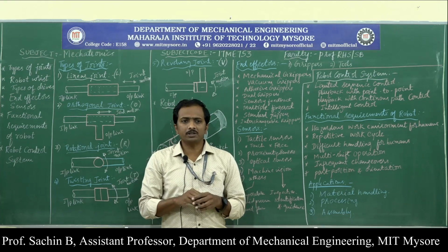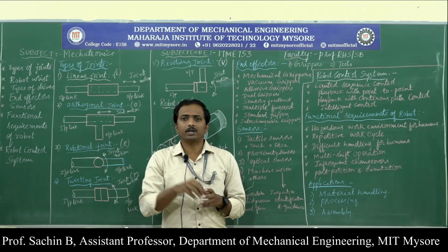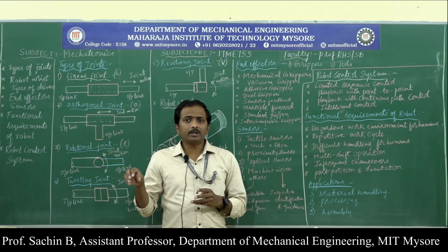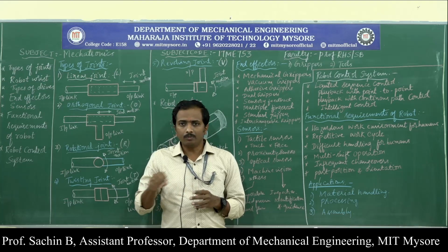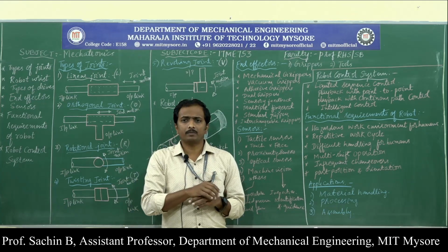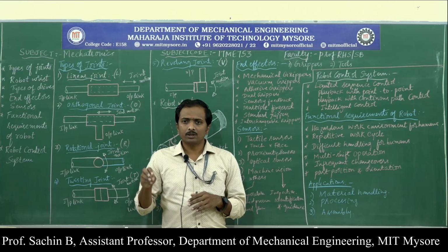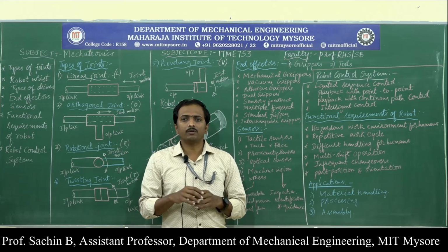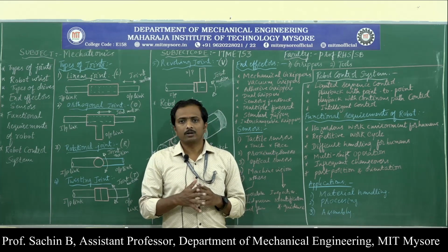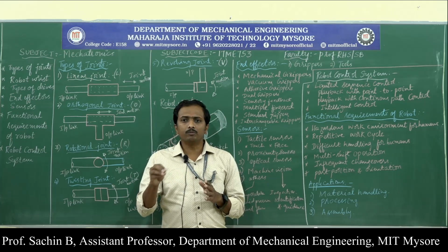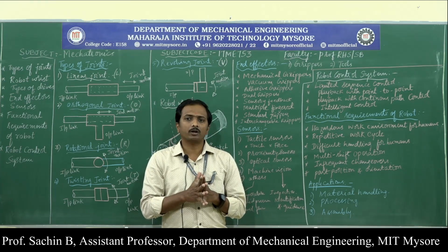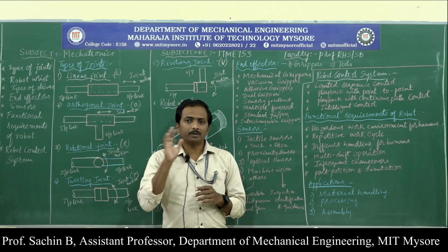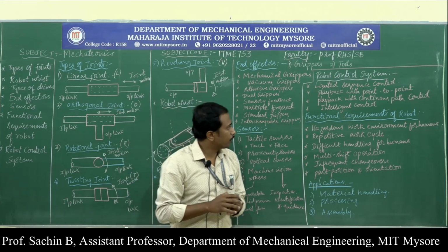Next, there is no need to teach the robot again for doing the same task. Automatically the robot will store the memory of that particular movement from one place to another place. Again it will do this task on its own. There is no need of teaching again and again. Once the new position or new movement has been taught to the robot, that is enough. It will operate continuously for a longer duration of time for the same task. That is about playback with point-to-point control.